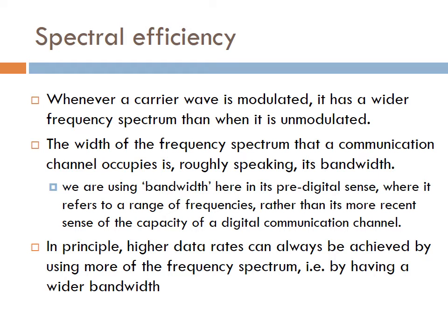The width of the frequency spectrum that the communication channel occupies is, roughly speaking, its bandwidth. We are using bandwidth here in its pre-digital sense, where it refers to a range of frequencies, rather than its more recent sense of the capacity of a digital communication channel, which we will talk about in the Shannon equation later on. In principle, higher data rates can always be achieved by using more of the frequency spectrum, by having a wider bandwidth.